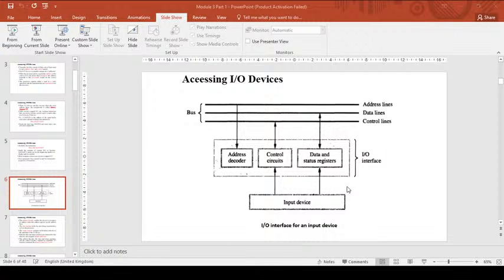So that is what is done here. Testbit #0, STATUS means test SIN; you are checking the 0th bit of the status register, which is nothing but the SIN flag. Branch if equal to 0 to WAITK. If SIN, or bit 0 of the status register, is 0, that means no key is struck and there is no data available in the DATAIN register.